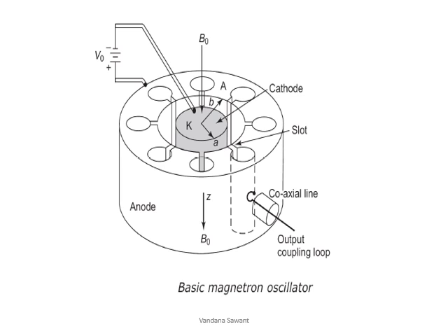Now this cathode is surrounded by a cylindrical anode. This anode consists of a number of reentrant cavities. The circles which are shown are the reentrant cavities. There are many reentrant cavities inside the anode. When these reentrant cavities are supplied with a high voltage signal, some noise is generated in the reentrant cavities, and this noise is in the form of an RF field. So the RF field is present in the reentrant cavities because of this noise.